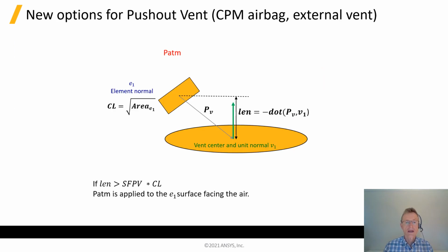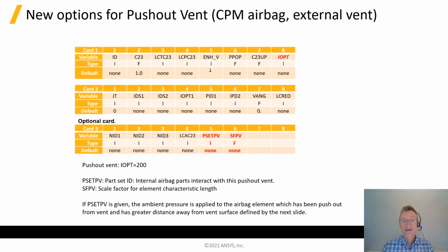And when modeling external vents, there's a new feature enabling the airbag particles to continue to apply forces to the vent cover right until it's flown a certain distance away from the edge of the hole. And this slide shows the input fields needed to invoke that new feature.